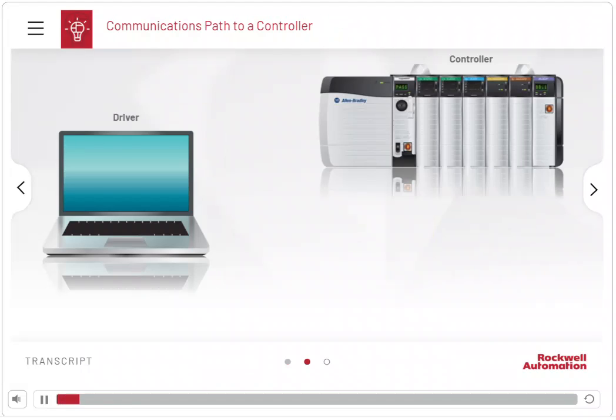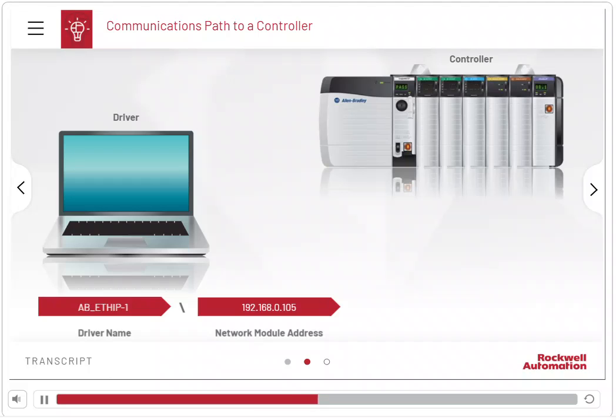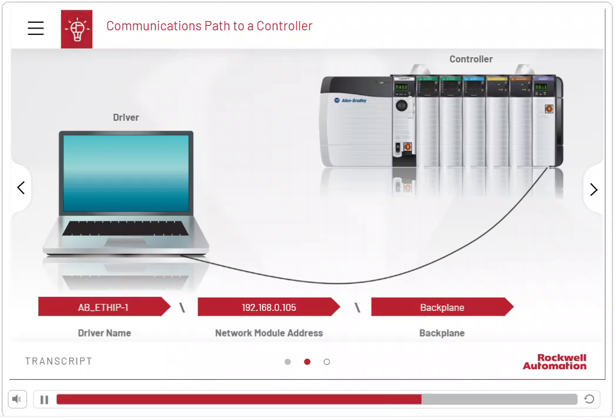To connect to a controller using the Studio 5000 Logix Designer application, you need to establish a communication path to the controller. A communications path is the path in which information flows through the networks and modules. The communication starts from the computer through the network driver, from the network driver to the IP address of the communications module, then to the backplane, and from the backplane to the controller slot, which is 6 here. You can also have a direct point-to-point connection using an RS-232 port or a USB port, depending on the controller.